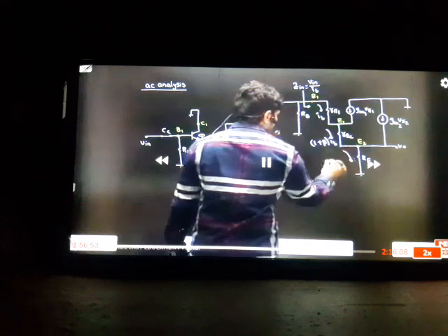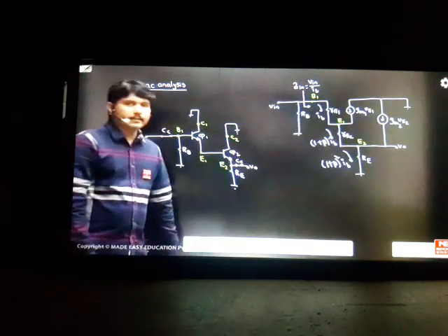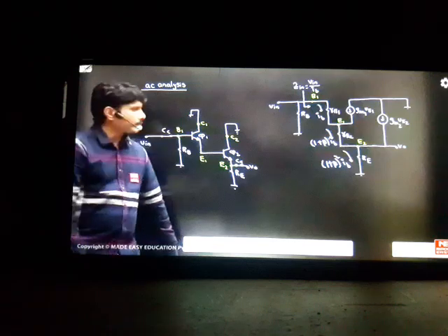One step if it is decreasing, it will increase by a factor of 1 plus beta squared times IB. So the currents will go like this, one by one: first IB, next 1 plus beta IB, next 1 plus beta squared IB. If you have one more transistor, it will increase like that. So current gains will increase very well in this concept.